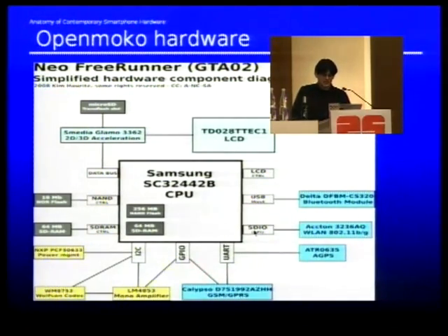we have an SDIO interface which connects to a Wi-Fi module, and we have a USB connect. This is not true. Is it? Oh, yes, it is actually true. Yes, it is true. It is USB connected, the Bluetooth, in this case. Yeah, because we ran out of UARTs. There is another connection between the Bluetooth module and the audio codec over here, but the person who drew that diagram, obviously it's hard to draw a line all across the diagram, but that's the PCM bus between the Bluetooth and the codec over here.